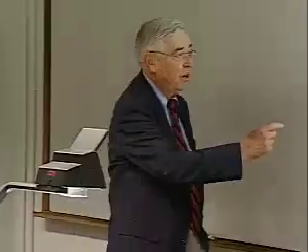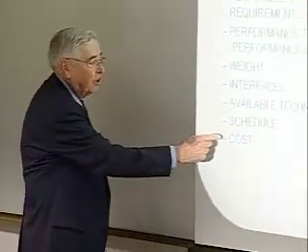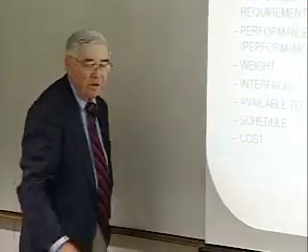Then we talk about the three-legged stool, as Professor Hoffman said. We talk about schedule, cost, and I put weight under performance. Because as I told you before, the first thing that's going to happen in designing a system is that the weight's going to get too high. Then you're going to find out that performance goes down. You have schedule slips. But the first thing that usually happens is you wake up one morning and find out, my gosh, my subsystem weighs a lot more than they told me I could have. So you ought to understand your weight.